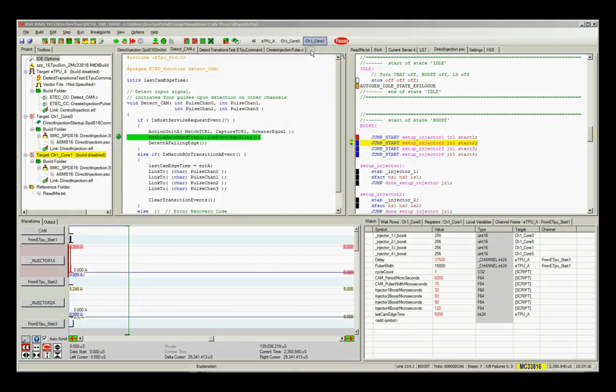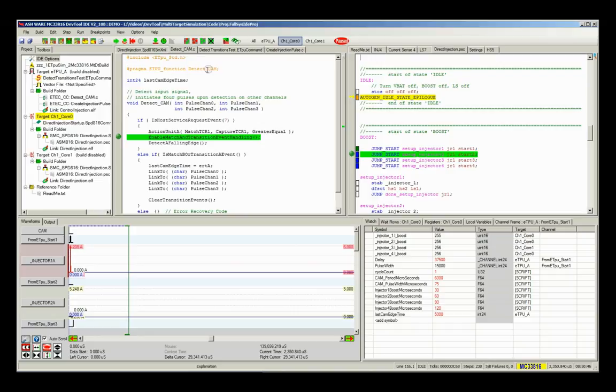So one purpose of the active target is to indicate which target caused the simulation to stop. But the active target has another function. It also tells the IDE which target to act on when doing target-specific things like stepping the code. So I'm going to activate the other MC33816 core, Core 0, by pressing its activation button. Then I'll single step it.